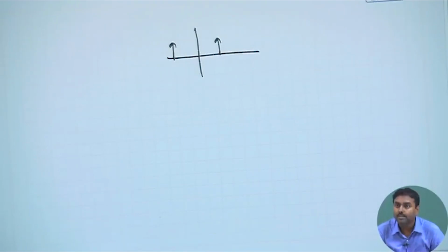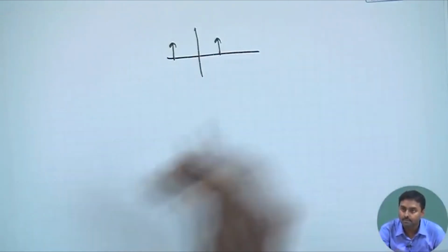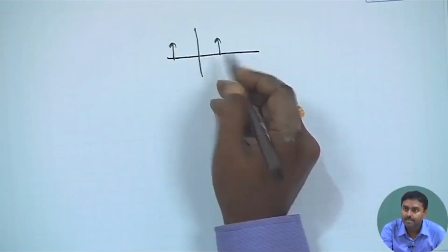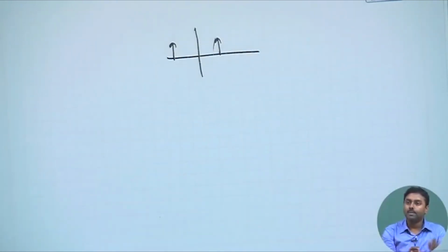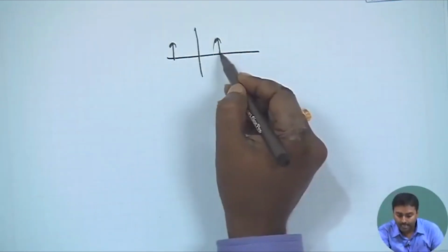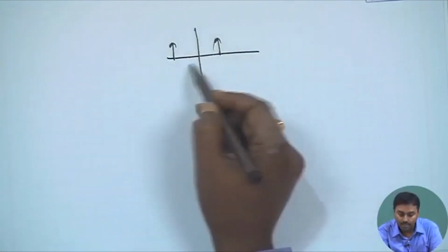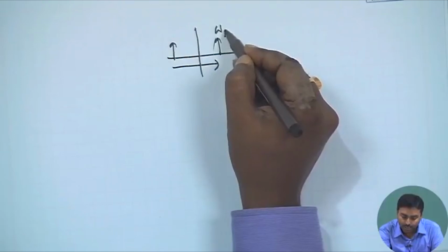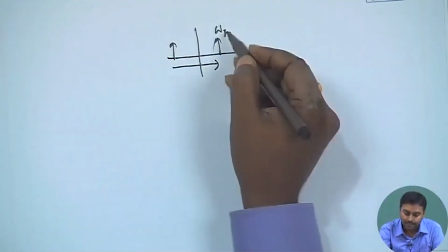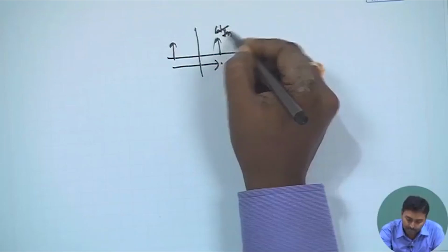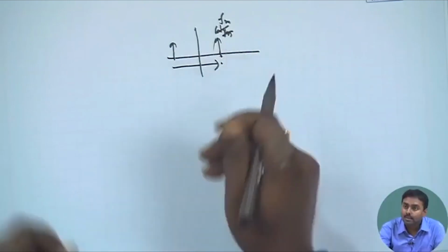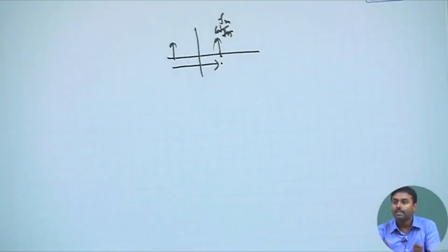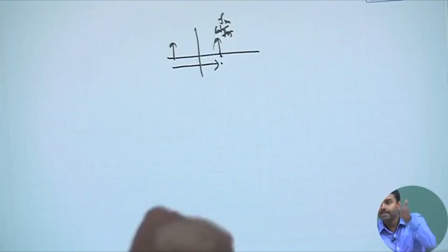If I just do it with a Nyquist frequency, meaning the sampling frequency is just matching the frequency of the sinusoid, then I will have a problem, because this is a band limited signal of course, with a bandwidth of, suppose this is omega m, let us say. If this is omega m, or if this is Fm, at Fm we have something. Okay. So, this is Fm. So, this is a band limited signal of highest frequency Fm, but at Fm it has an impulse.